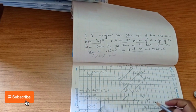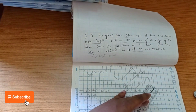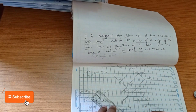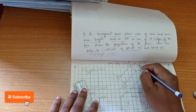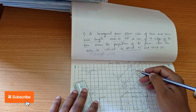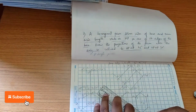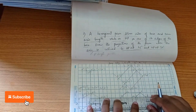This is connecting here, and this outer boundary line is done. Now visible space, as it is looking from the top view, we are able to see this face. So the top hexagonal face is visible. So we write the hexagon here. Okay, and this rectangular face is also visible from the top view.